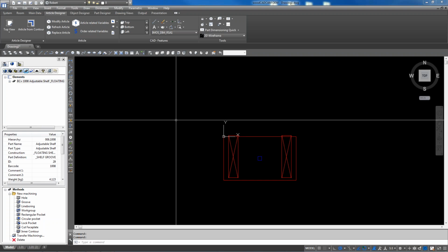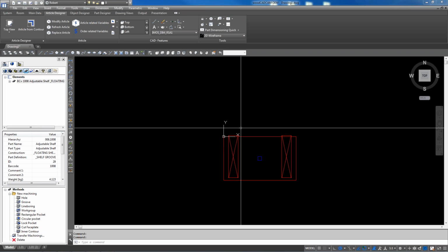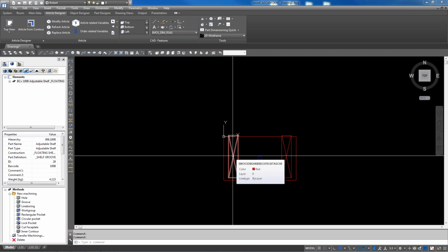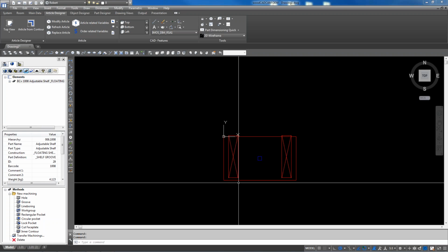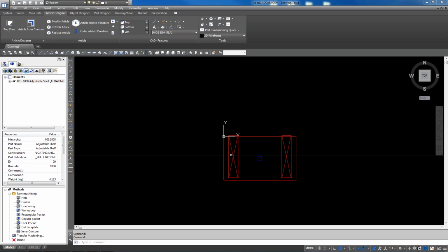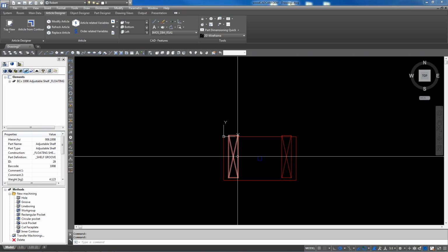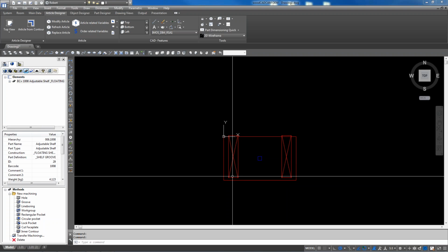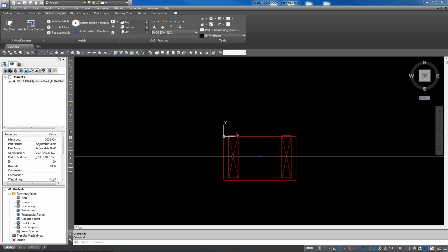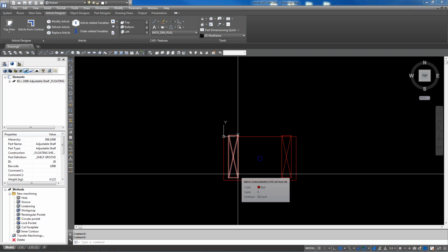I didn't catch, Larry. What is that 9.5 number from? So for a rectangular pocket, this works off the center. Oh, okay. Not a distance from the edge. So that's why in X I said 4 inches, because we wanted 2 to the center, because it's 4 inches wide. So front to back, you need a 17-inch route. Half of that is 8.5 plus the inch you want here, that makes the 9.5. Okay. I just added a quarter to that, moved it back a quarter, and made this a 1/2 inch longer. So it's still 1 inch from the front, but it goes past it on the back. All those rectangular pockets, grooves, rectangular circles, they all work off the center. Got it.